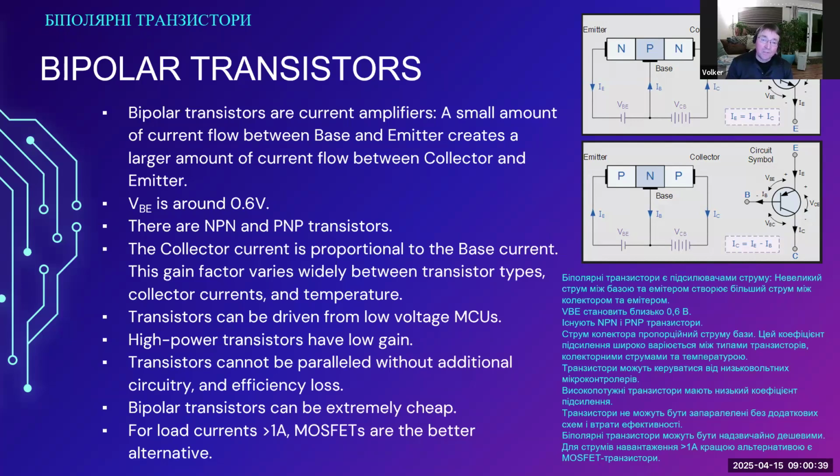But the bipolar junction transistors never quite go away because they have some characteristics that make them still very usable in circuits with microcontrollers. And one of these characteristics is the basically low voltage that is needed to turn them on. And that is about 0.6 volts.